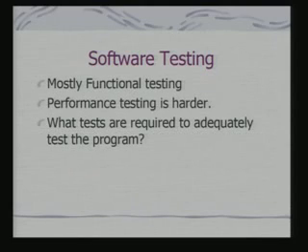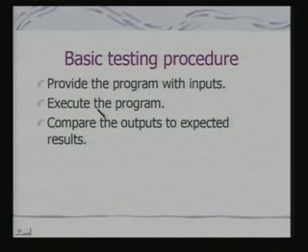Now, similar testing has to be carried out for the software as well, because software is a driving force behind the hardware. We can check the hardware circuitry, but when and how to use the hardware circuitry would be determined by the software running in the embedded system. So, testing of the software for embedded systems is also critically important. The basic testing procedure is to provide the program with inputs, execute the program and compare the outputs to expected results. That is the same as that of the hardware.